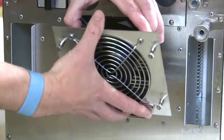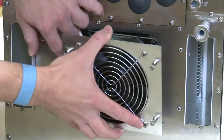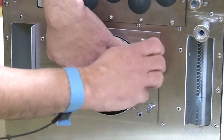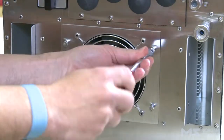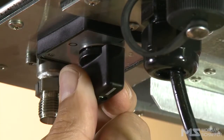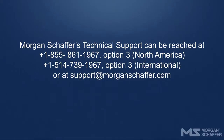Connect the power supply for the new fan, ensuring that it is fully engaged and locked. Place the fan in position, taking care not to trap its wires. Manually tighten the fan's 4 screws. Complete the tightening using a flat screwdriver. Restart the Calisto. If the problem persists, please contact Morgan Schaefer for assistance.